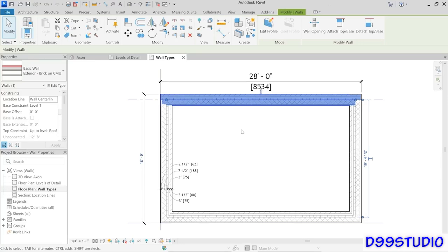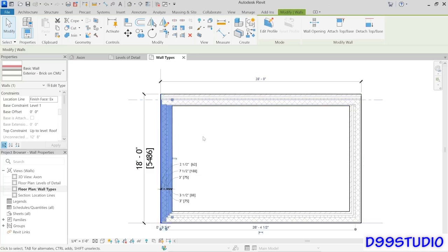Each wall has its own orientation. That worked well because of a feature called location line. And the location line of that selected wall was right here along this dashed blue line. In other words, right along the center of the wall's geometry. So if you flip the wall along its center line, it flips in place and the dimensions of your building are unaffected. Well, let's contrast that to the behavior of this wall, which I intentionally set the location line to something else.